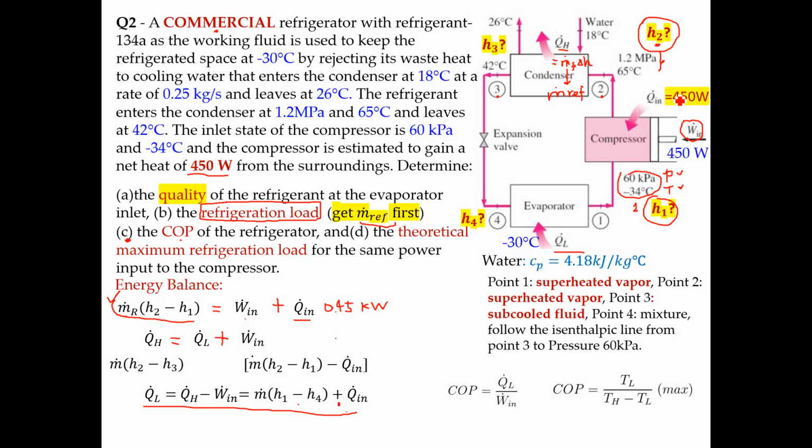Just make the distance from the compressor and evaporator a bit shorter, because the fluid will absorb heat from the pipes as well. Because I suspect that is quite complicated. If you have it superheated in some stage, and if you follow this isentropic law, it actually would end up at a higher condenser temperature. Although we know this would give a little bit more cooling capacity, it might make the efficiency of the condenser lower. So it would be really complicated unless we know all the exact values and do the calculations.